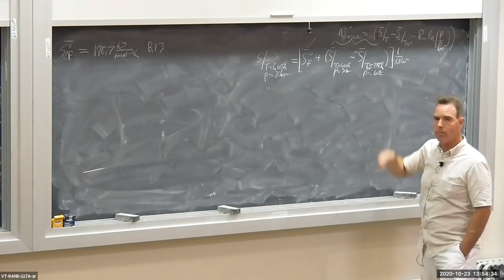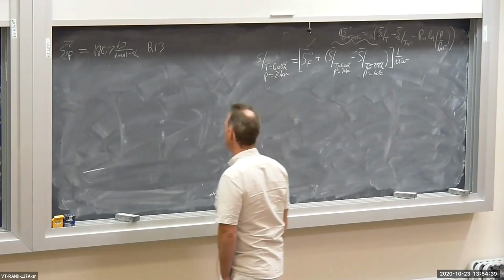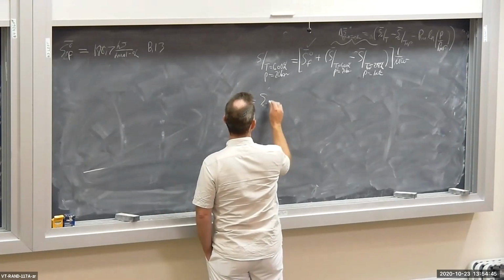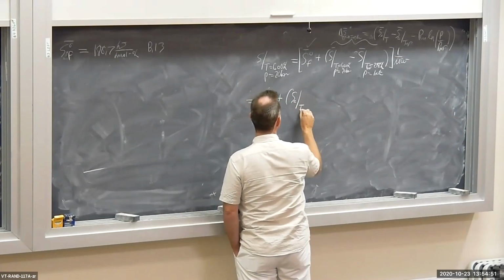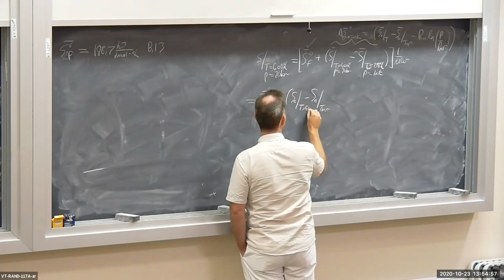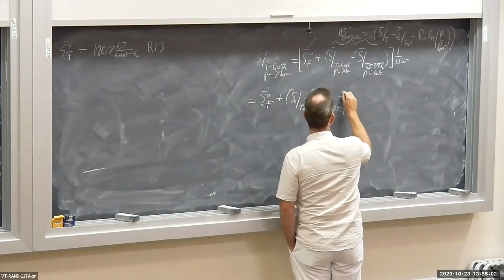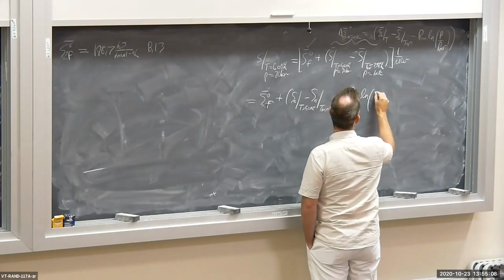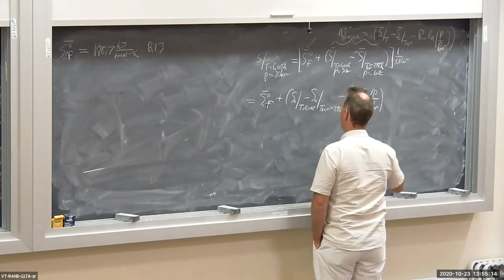So that's what this whole term is. Okay, I'm using the S naughts in there, so I need the S naughts. I guess I better write the whole thing out again. So this is S naught sub F bar plus S naught evaluated at T minus S naught evaluated at T ref. That's 600 Kelvin, and this is 298 Kelvin. And then I have minus the universal gas constant, and then I have P, which is 20 bar, and P ref, which is 1 atmosphere, okay?